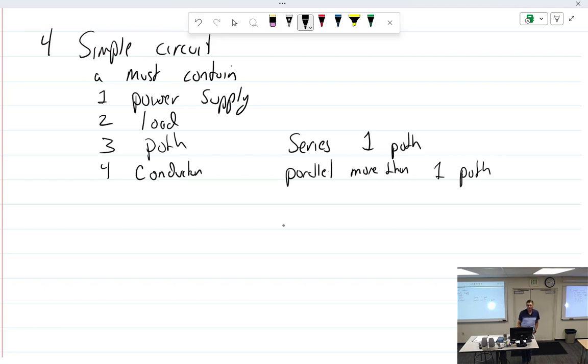Ground? No, not a ground. And we want to be careful with, and I'm glad you brought that up, how we say ground. Because when we're working with DC circuits, our ground is our return path. It's really the return wire. As opposed to AC and our wall sockets that have three wires. The black, the white, and the ground wire, which really is not part of it. That's a safety part. The power goes through the other ones. They're going back and forth through the black and white. The ground's a safety, so it can leak to ground. You don't need it. A lot of homes didn't have it a long time ago.